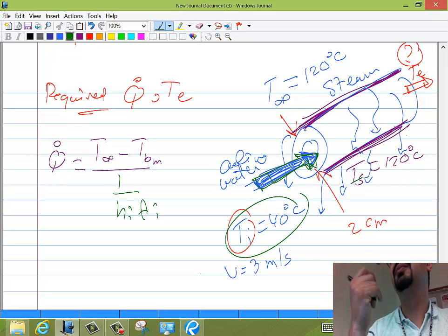Is there a way to solve this mathematically, or do we have to guess the temperature and find the average? At this stage, you can actually guess the temperature by guessing an H. If you have solved problems, or you open a textbook and find the typical H for such velocity, you can use this to guess a temperature in the exam.